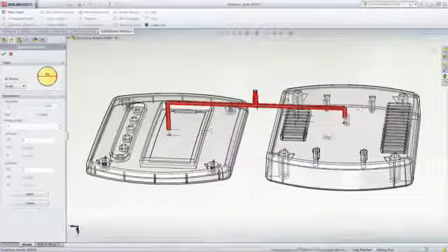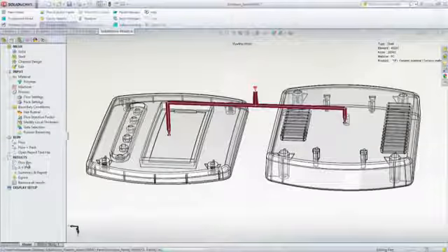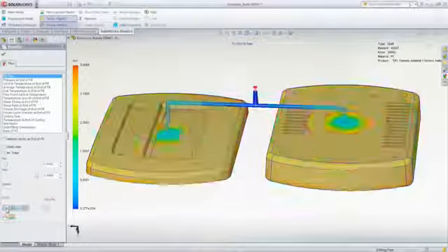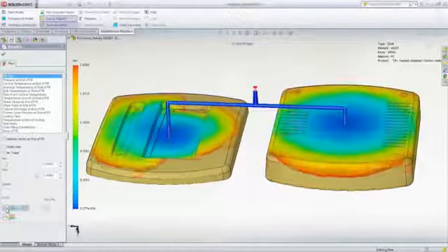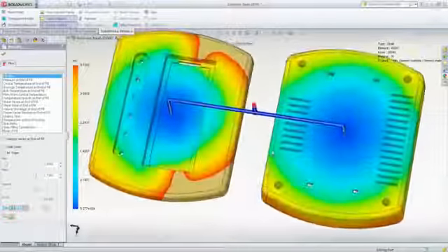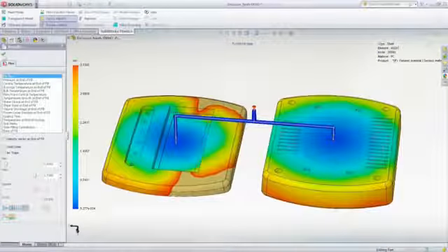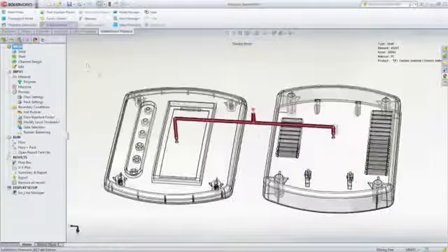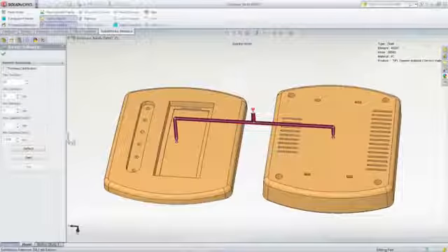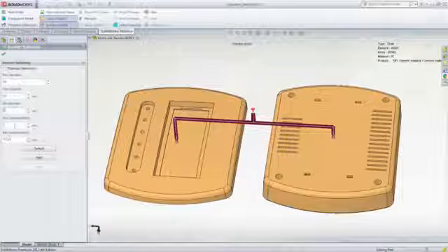However, an additional challenge is introduced because when you mold two or more parts of differing geometry in the same mold, your goal is to get all the mold cavities to fill at the same time. And this can be virtually impossible to achieve without the use of SOLIDWORKS plastic simulation. The good news is that you can perform a runner balancing analysis in SOLIDWORKS Plastics. This is a multi-iterative analysis with the objective of filling multiple cavities of differing geometry at the same time.